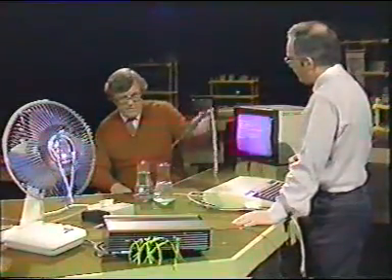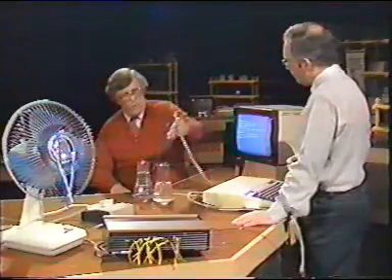Because we were showing it actually in the ice or in hot water, but normally this would be standing in the air almost like a thermostat, and you get continuous variations, so it will be a closed-loop feedback mechanism. That's right. If you have it actually sensing the temperature of the air and then changing the temperature of the air, that's called a closed-loop feedback circuit, and that's a very fundamental, important concept.